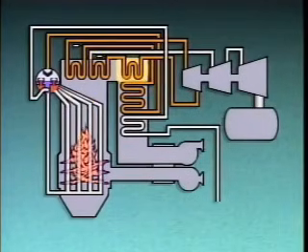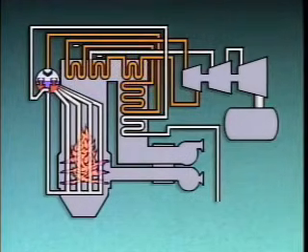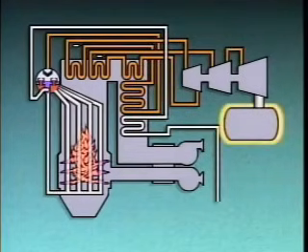The primary reheater is located farther from the flame, and it receives most of its heat by convection from the hot combustion gases, so it can be classified as a convection reheater. After it's reheated, the steam in this steam flow path flows to the intermediate pressure, or IP section of the turbine, and then through the low pressure, or LP section.